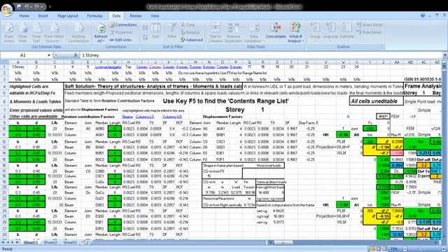Let's say WL square over 8. WL square over 8. It's some formula, that is bending moment, we call it bending moment. I'll write this for your better understanding: bending moment, simply supported beam. Well, so this is now W.